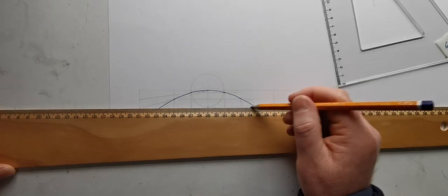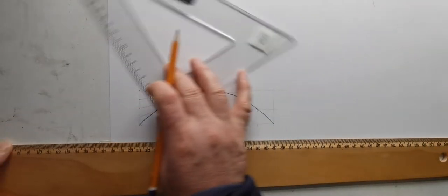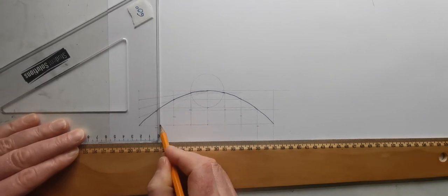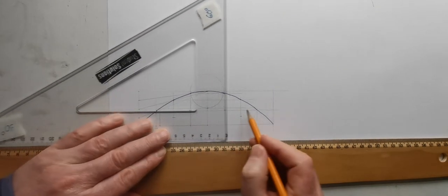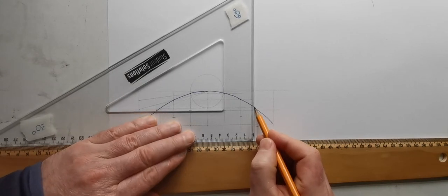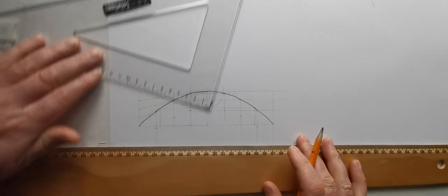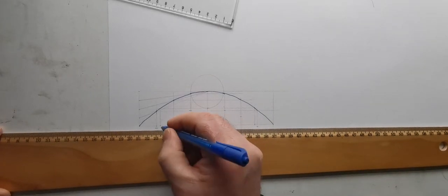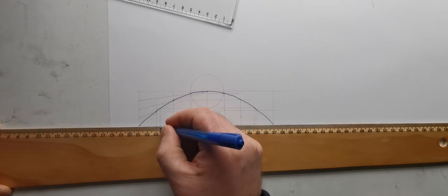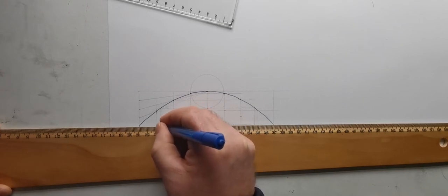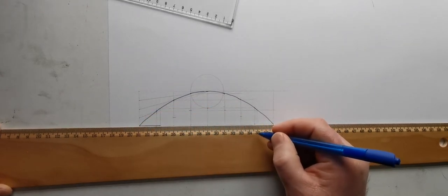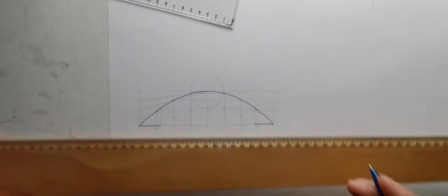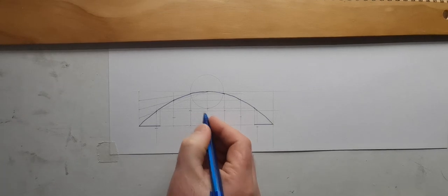but if I wanted to know exactly where it crosses the line here, just take a horizontal from the bottom of the circle over, and where it hits the curve here, come down, that's where it crosses the horizontal here. So I know now that that's the point D there, the flat one coming in, and this is point F, and the rest of this I'll draw.